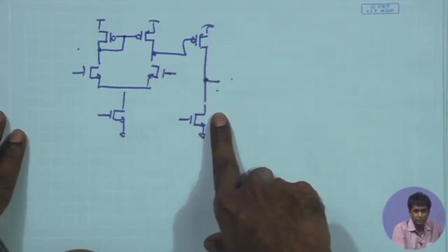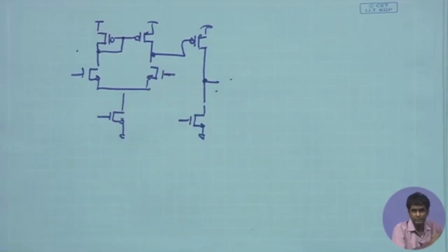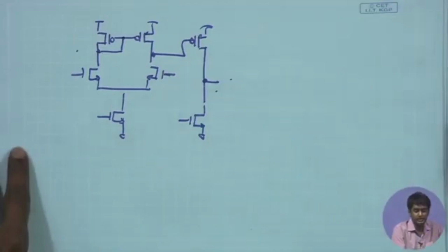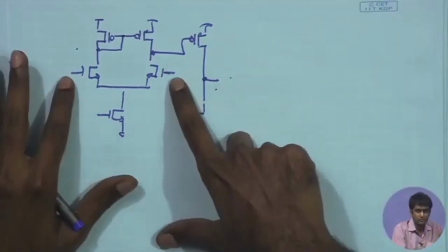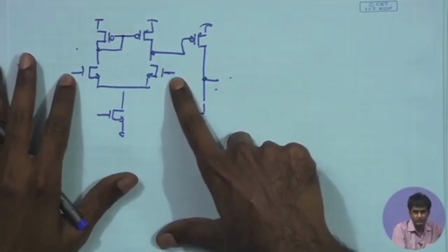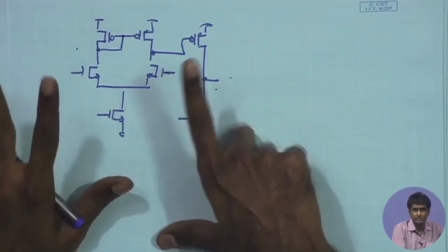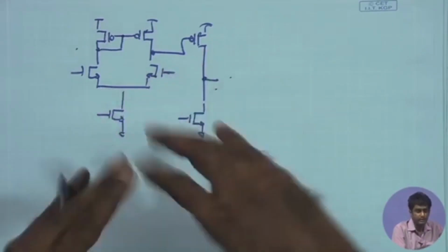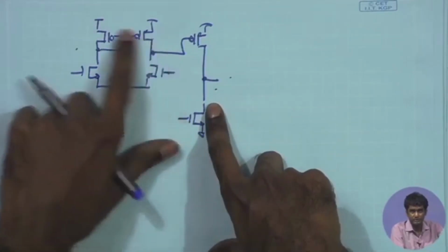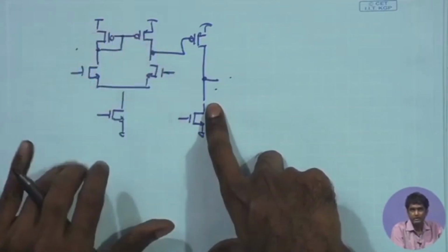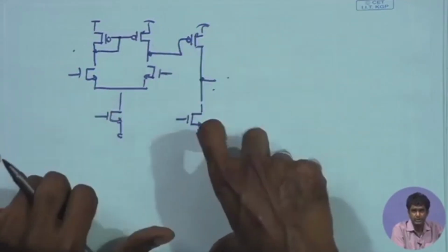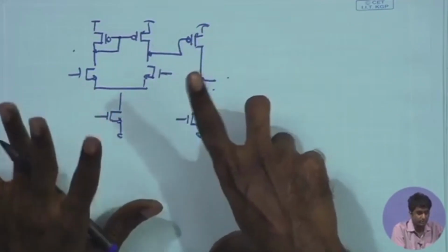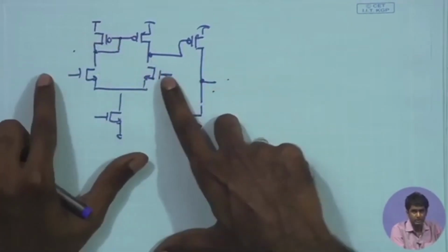Remember, however, in order to obtain the frequency response when you're trying to judge your amplifier for meeting the required gain bandwidth constraint, you need to use the appropriate DC bias point so that you can take the frequency response. Frequency response, remember, is a linear analysis where the simulator uses the linear, small signal model of the amplifier. And the small signal model needs the transistors to be in saturation. Therefore, in order to use the frequency response, you must make sure that you are applying a proper DC bias